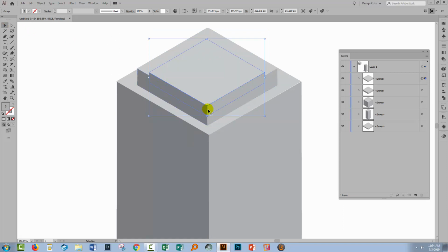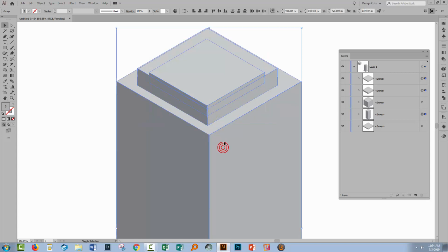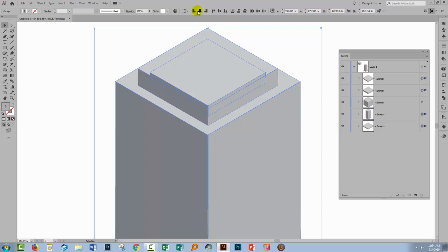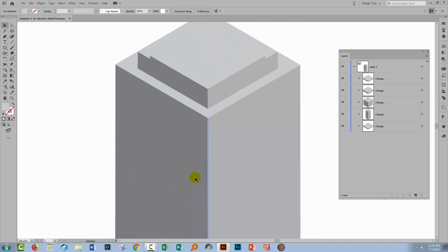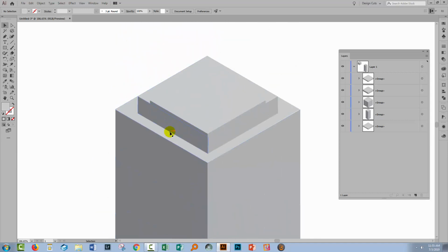You want to line up this vertical edge here so the edge is exactly the same on all three shapes. So you can select all three shapes, go to the Align tools. You're going to choose Align to Selection, and it's going to be critical that you have all of these objects selected when you do so and that they're grouped. So I'm going to include the base in this at the same time, and I'm just going to click here on Horizontal Align Center. That just makes sure that all the elements here are perfectly lined up in a vertical direction along this axis here.